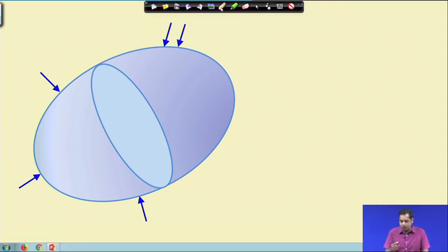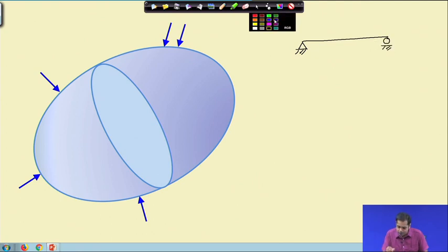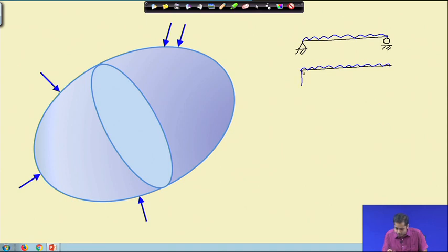Before that, if you recall your first year mechanics or structural analysis, if we have any beam, say a simply supported beam, which is subjected to some external loading, right. Now, if we draw the free body diagram of this beam, it will be something like this. We have external loading on this, and then we have reactions at this end. This is a hinge support, that is why 2 reactions, and at the roller support we have 1 reaction. Okay. And now, if we take a section at this point and divide the beam into 2 parts. Okay. Now, this is one part and this is another part.